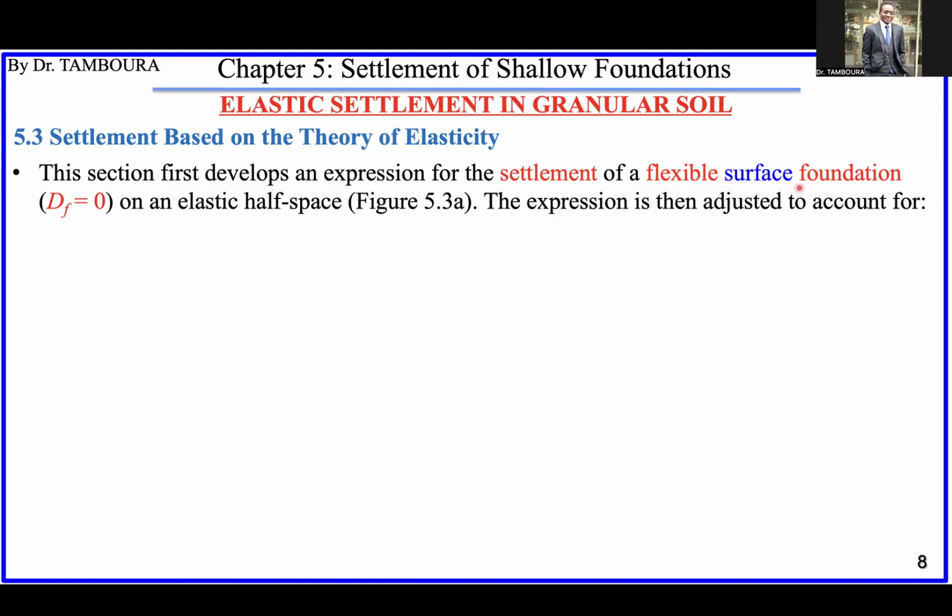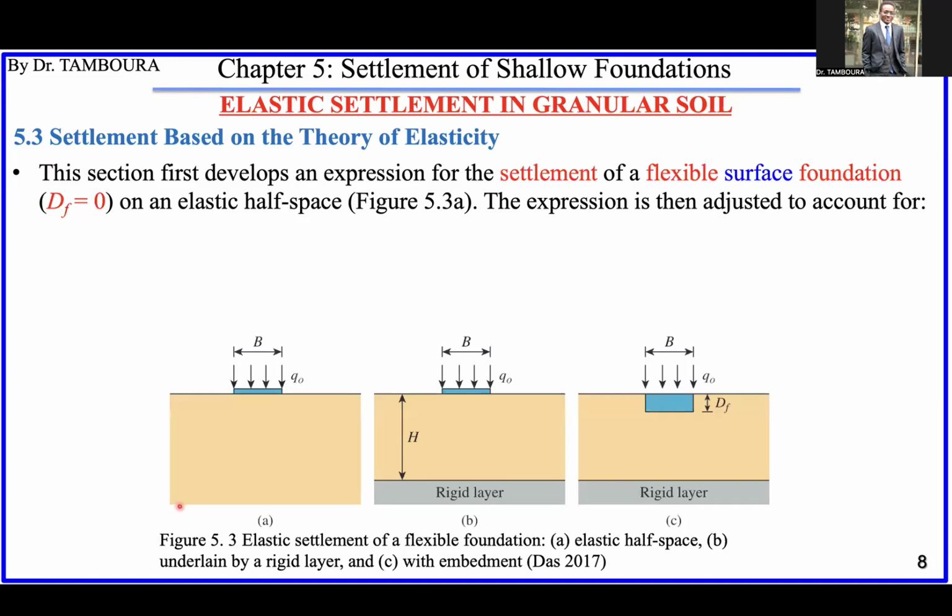That is important. Surface means what? It means the footing is not embedded. Okay, and flexible, you know already. Okay, flexible: the pressure is uniform, but the settlement is not uniform. So here is an illustration of different cases of foundation you may have.